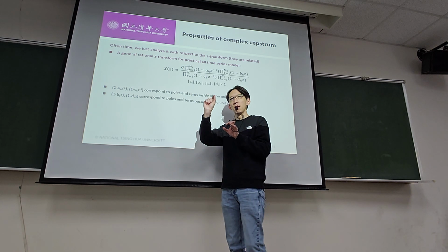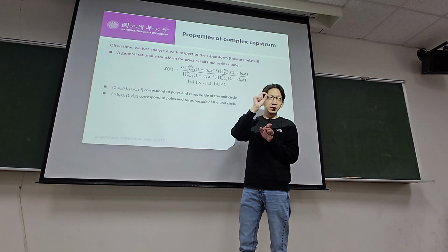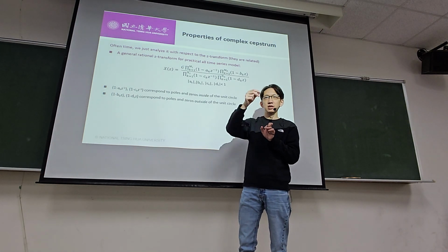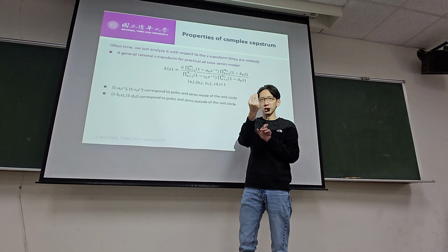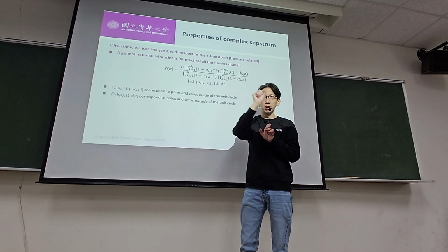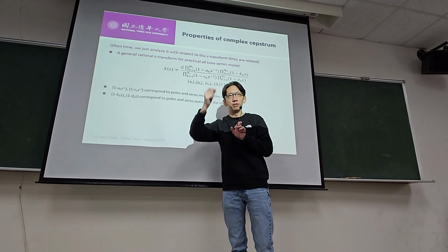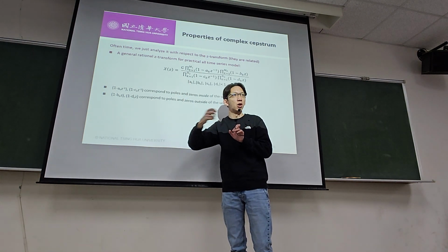If you have poles exactly sitting on the unit circle, what does it do? It has no decay and it also doesn't increase, because poles are either inside, outside, or on your circle. On the circle, you have a completely oscillating signal. It doesn't converge, but it doesn't go out of bounds either. It always oscillates.